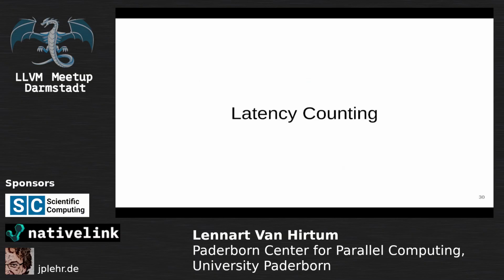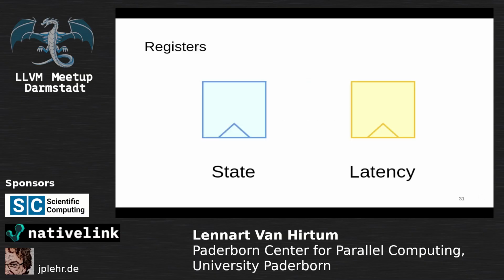So then we've come to the latency counting part of the SUS compiler. Because in my experience, when people build hardware designs, they generally tend to use registers in two distinct ways. Either the registers are part of the core functioning of the design, like the cycle-wise behavior of the design would not work without these registers.